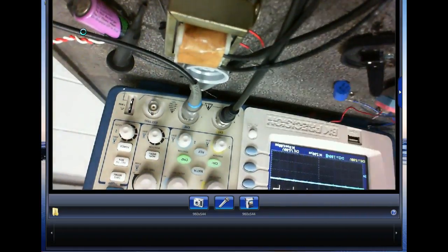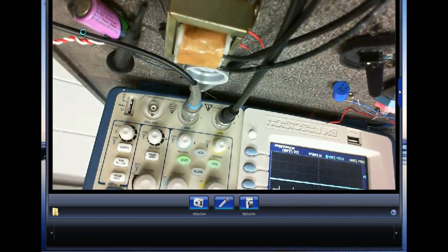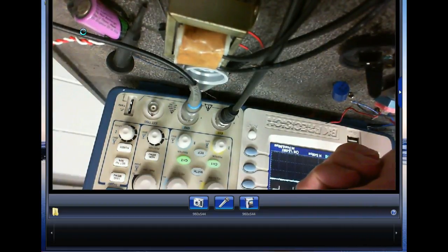But what we're doing with our transistors is the elements that are working, they're either all the way on or all the way off. How much power does a closed switch produce? None, because it has no R. So you might have 10 amps worth of I, but its power is equal to V times I. So if I turn my transistor on all the way, we call it saturation, it's still going to drop a voltage, but it's not going to be hardly any. And then we turn it off. How much power does an open switch dissipate? Now we got a lot of voltage, but we have what? No current. So what we're doing on these transistors, we either turn them wide open or we turn them off.